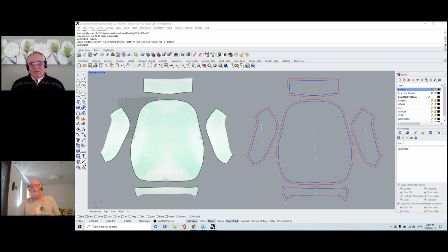All they need is the parameters of the textile. So if you're a textile inventor, you have to test your own textile and tell ExactFlat what its moduli are in bidirectional moduli, and it uses that information and only that information for the flattening process.